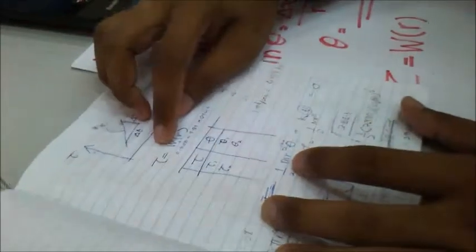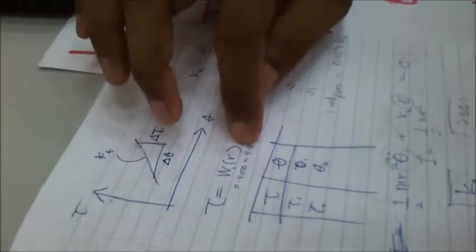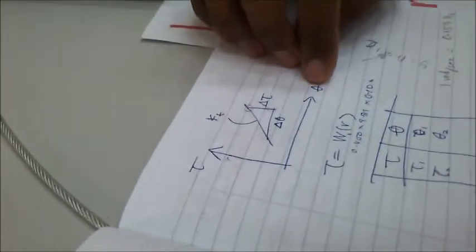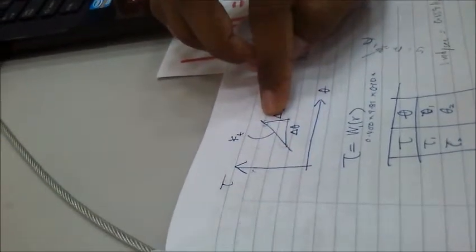We use this data to complete the calculation of the tau, and the data is used in the formula to find the tau. The tau is on the y-axis, and the angle in radians we put on the x-axis. So when we put it in the graph, we will get an inclined line. The gradient is the stiffness.